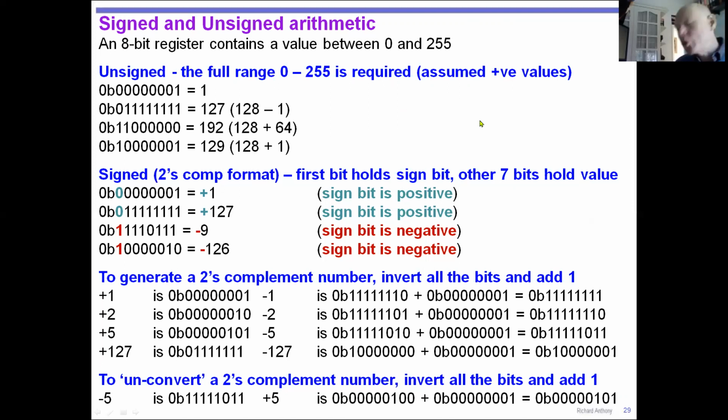And in my code, you'll see I often use unsigned characters as storage because that guarantees an 8-bit store, which I can use as a numeric value, by the way, but it optimizes the memory use. So you'll see that I do that sometimes. Unsigned char as a data type just says use an 8-bit store because integers are normally 16 bits. So if I only need an 8-bit, I can use that variable type. So let's assume we are working with this kind of storage. We're trying to optimize memory.